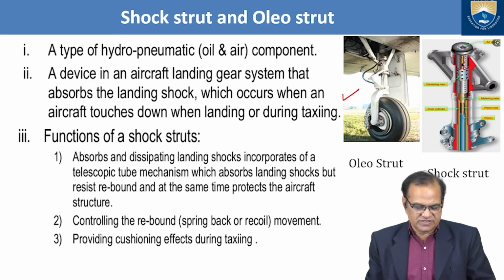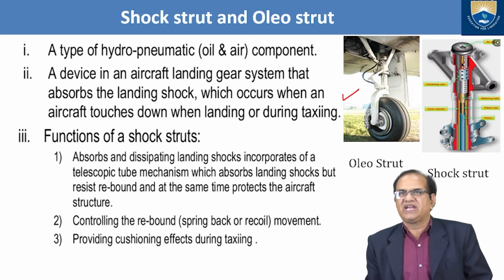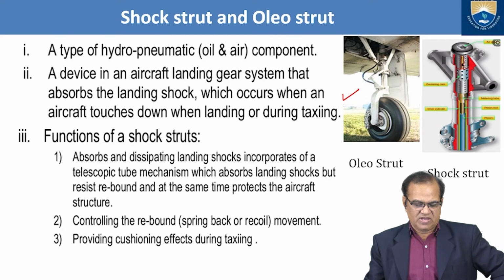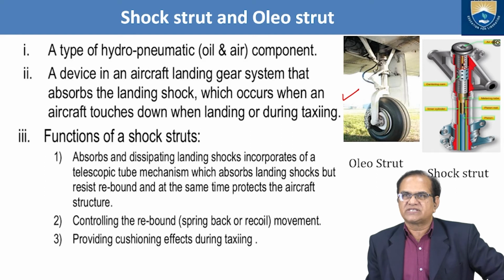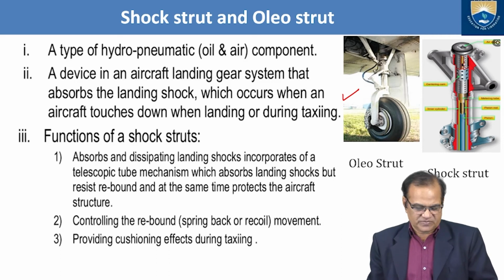Functions of a shock strut: absorbing and dissipating landing shocks. It incorporates a telescopic tube mechanism which absorbs landing shocks but resists rebound and at the same time protects the aircraft structures.